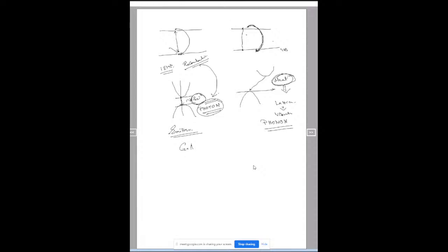Example, gallium arsenide is a direct bandgap material. So recombination will be direct recombination with emission of light. But in the case of silicon or germanium or many other 3-5 materials also, not all 3-5 materials or 2-6 materials are direct. There are a lot of indirect materials also in 3-5. So there the energy will be released as heat, not as a photon.